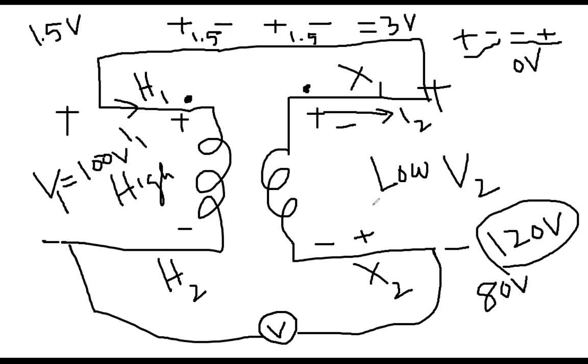So when you are getting the lower reading, you will be telling that, okay, this is the subtractive polarity. And when you get a higher reading than this one, it should be the additive polarity. This means minus should be here, plus sign should be here. Does this make sense?